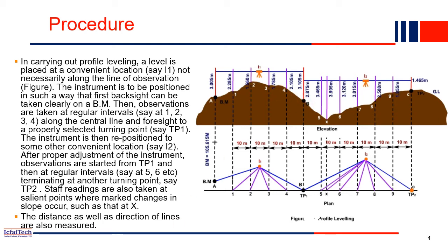So for example, the road you are constructing has a curve. So for example, let me, yeah, so some bend is there. If any bend is there, although 100 meters may be here, as there is a bend, in the bend also we take one full station.